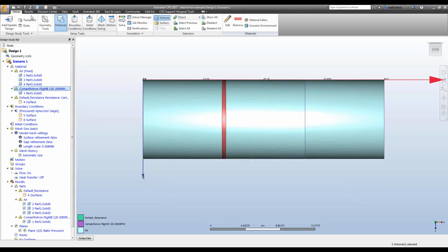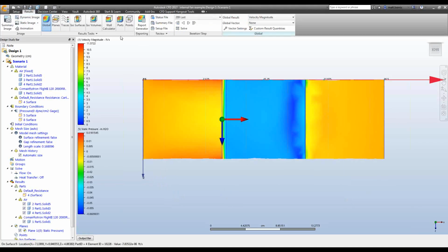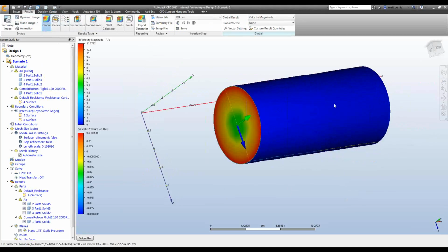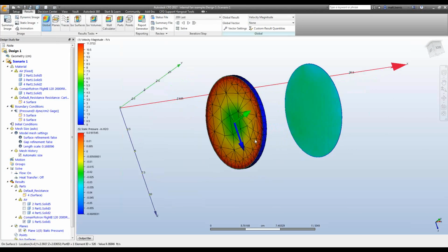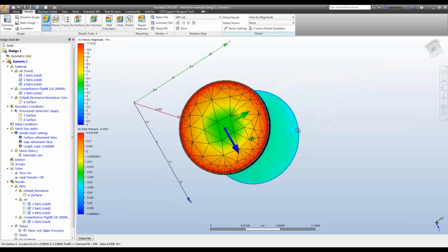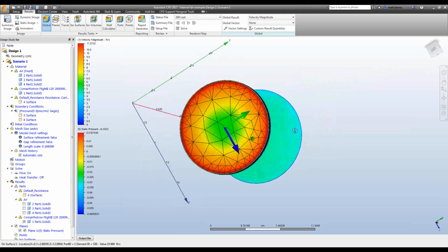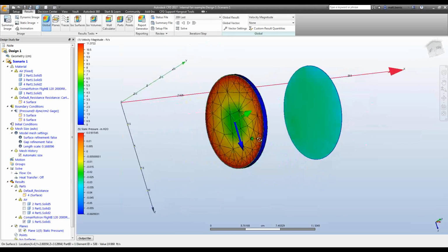One other comment about the meshing is you want to use a uniform mesh on the internal fan components. Pretty straightforward. That doesn't look uniform to me. So that could have been my mistake, but it's considered a best practice to use a uniform mesh just on the internal fan component.